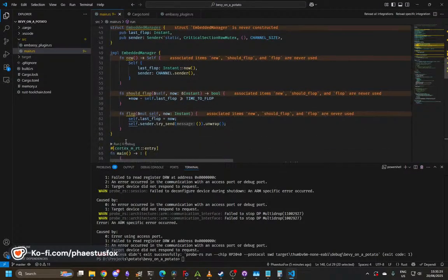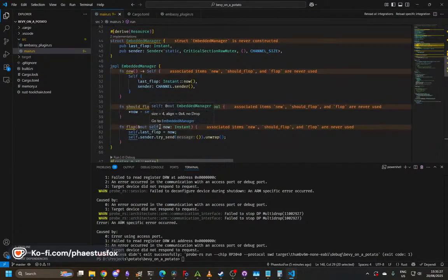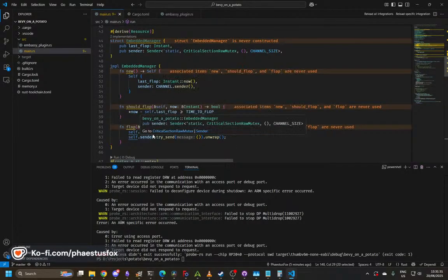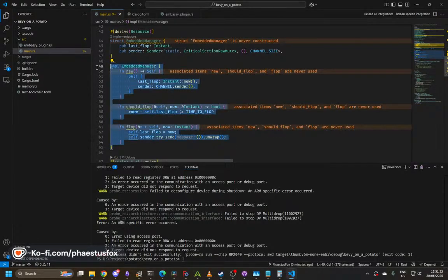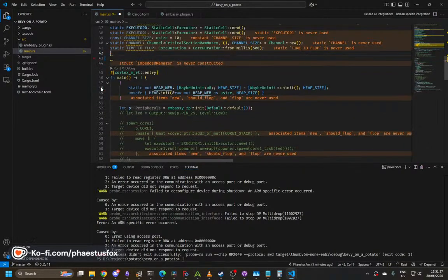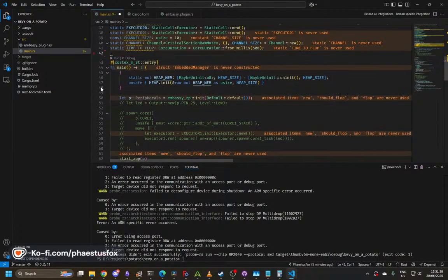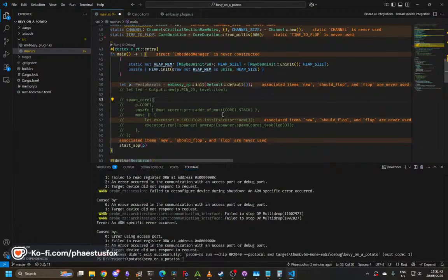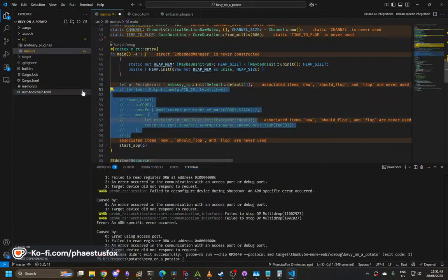One thing I need to do is probably turn the clock cycles down, because I'm going to be using e-paper, which has a horrendously slow refresh rate, which means I really do not need the CPU running fast. So if I can turn the CPU speed right down to get better power consumption, that would be best, because the project I have in mind needs to be stupidly efficient.